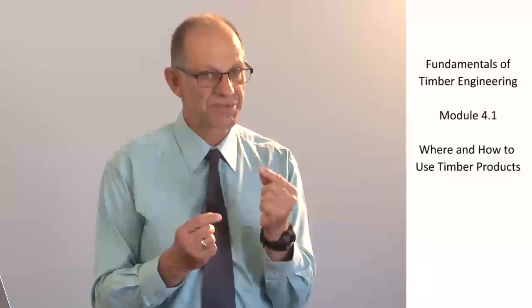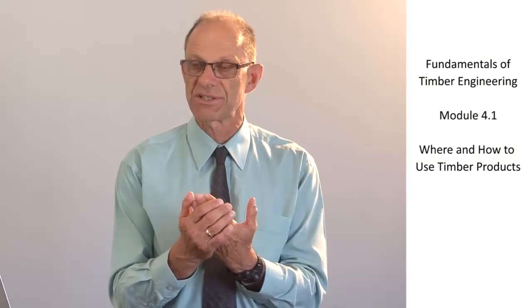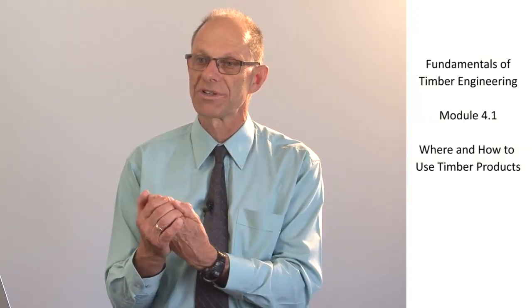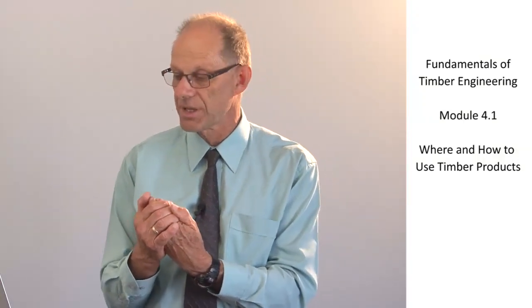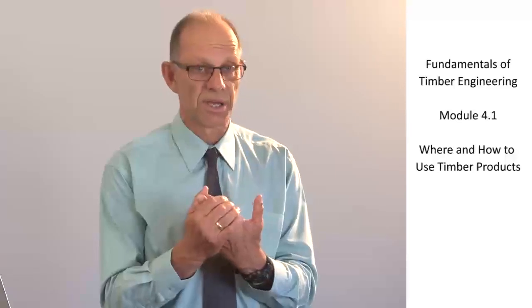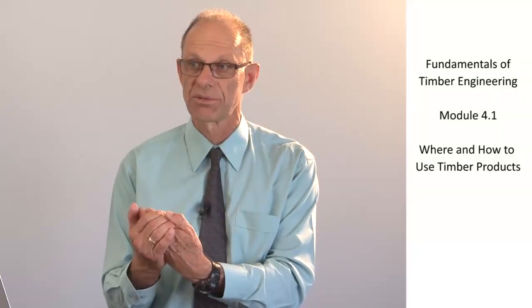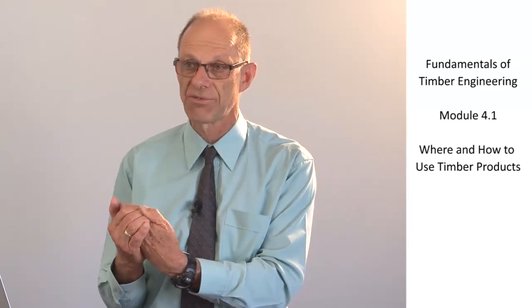And we have to have some assurance that the timber is actually going to be able to resist unseen, unwanted guests like termites. If it's outside above ground, it's also exposed to the elements, which includes sunlight and water. And in that kind of environment, which is a harsher environment on the timber, we call that an H3 environment.